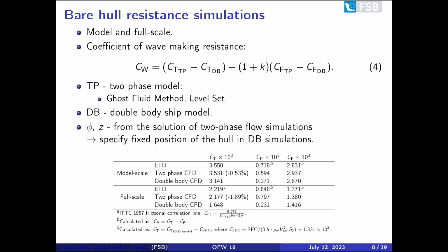If the obtained results in the table are observed, it's visible that with the larger Reynolds number achieved in full scale, the frictional resistance component is less dominant in total resistance. Overall good agreement with the experimental value of total resistance is achieved, satisfying the condition for conducting self-propulsion simulations with sufficient accuracy.